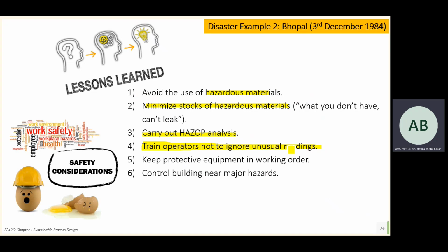Low level is 80. Okay, usually your process maintained at 100. Suddenly one day you saw your process goes up to 110, but not yet reaching the upper level. So what you should do? Do you just say still in the range, so don't have to do anything?